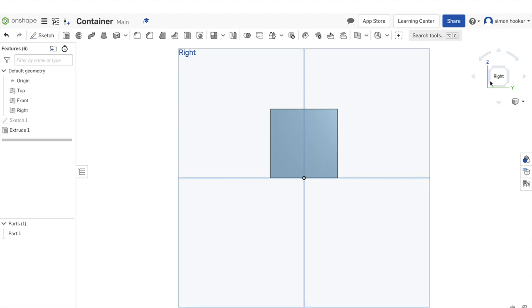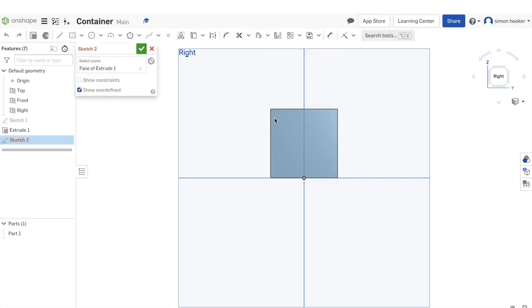So I've just clicked right, you might have missed that because I've just had to change the video slightly, and I'm going to do another sketch and I'm going to click on this surface, and we're then going to draw, I'm going to use a corner rectangle this time. I'm going to draw it in like that, so it goes all the way to the bottom. Notice the mistake I've just made, I didn't want it to go all the way to the bottom because I'm putting doors on this. So we're going to go from the top onto there down,